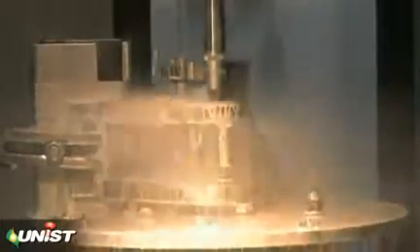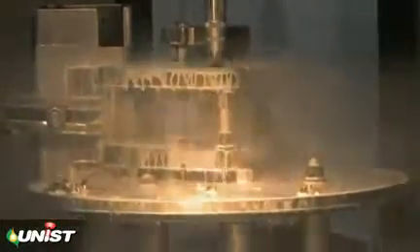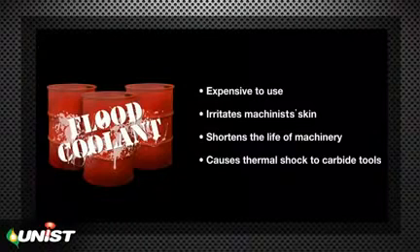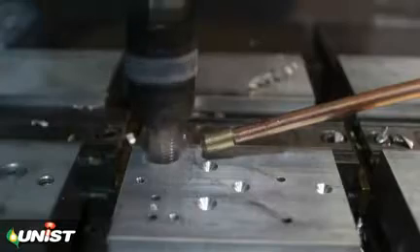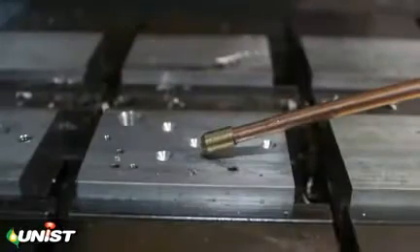The use of coolant can also cause thermal shock to carbide tools, resulting in microscopic cracks, which weaken the tool and can ultimately lead to tool failure. The negative aspects of flood coolant, along with the fact that it requires costly government-regulated disposal, make flood coolant an expensive and ineffective proposition.